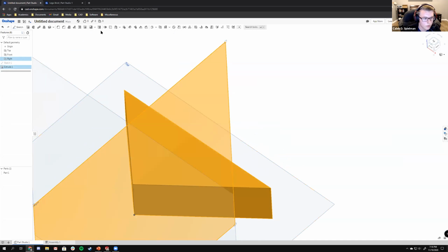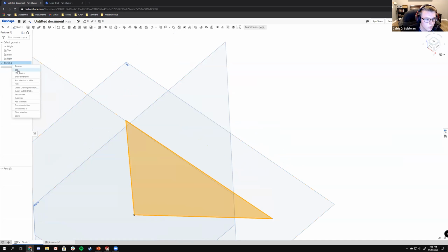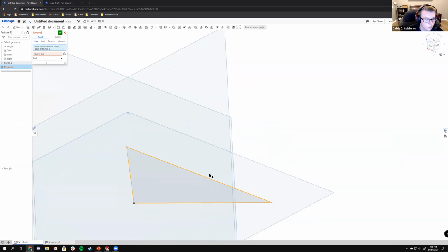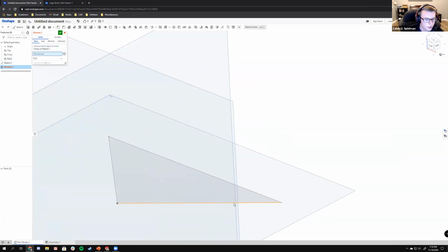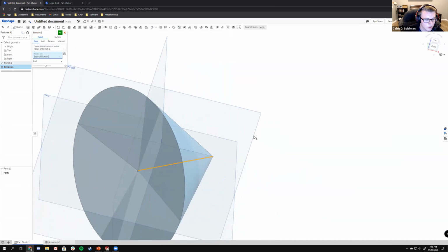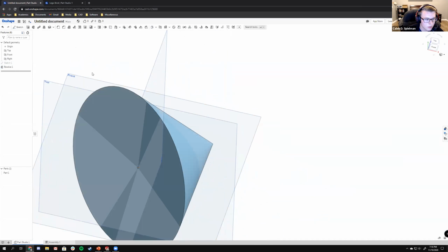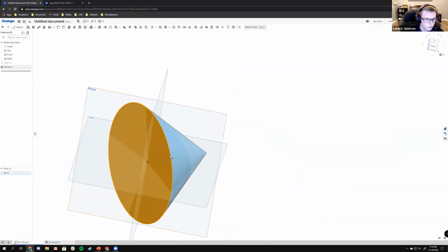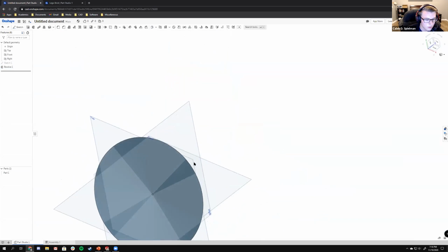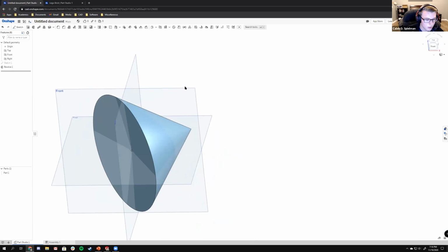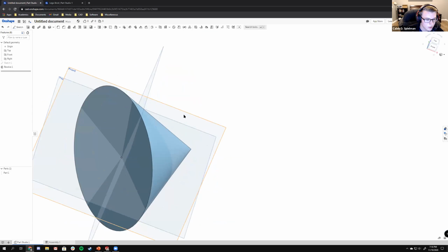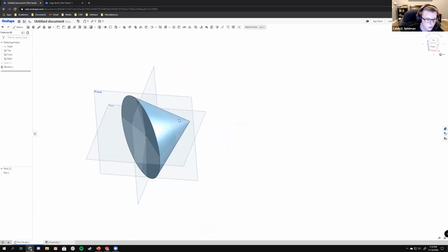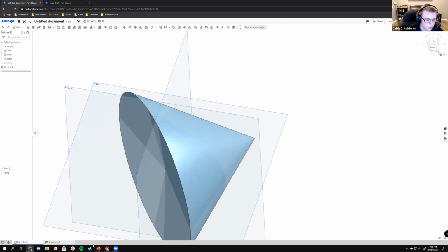And of course, the Revolve tool is as well. I'll show you here. Here's the Revolve tool. It's already selected the contour, so now we just need to select an axis. Check. And now we have something resembling a cone, although it's not the cone, not exactly. So those are basic solid bodies, basic solid body features in SolidWorks and Onshape to create volumes. You'll be using that a lot, of course. Sorry, Onshape is very disorienting. There we go.